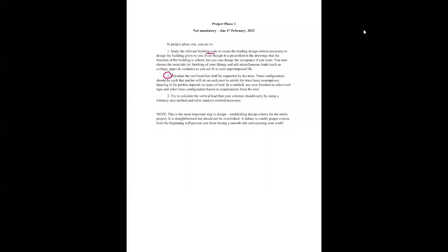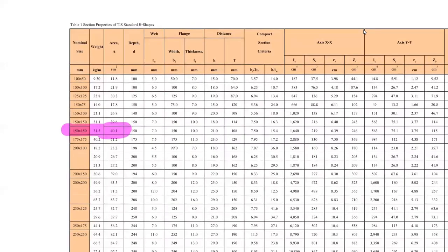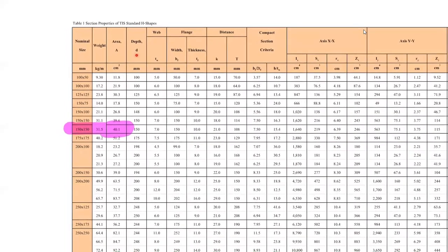If you plan to calculate, notice that, sorry, one more time. This is depth. This is not H. When you want to calculate the slenderness ratio of the web, you must use H, which is equal to D minus 2K. K is here also provided. Okay. Use that, that's fine. So we are okay with that, I suppose.